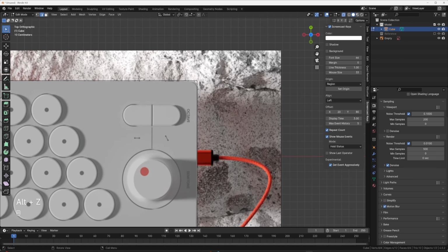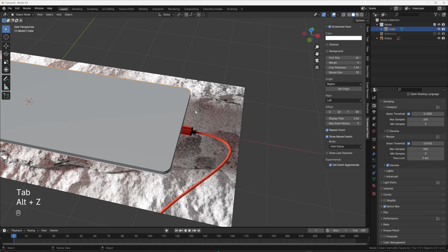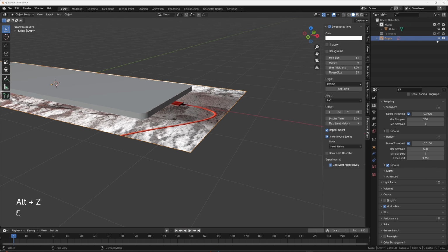Basically, I just want to make sure this bevel is pretty much the same. So I'm going to do Control B and then scroll my mouse wheel up. I'm going to do 10 segments. And we're basically just wanting to get this close to the design that we have here. Okay. Out of Alt-Z, that's set. I'm going to hide the reference image again.